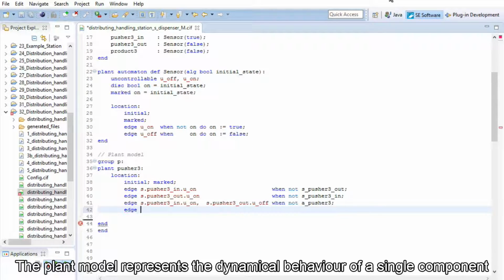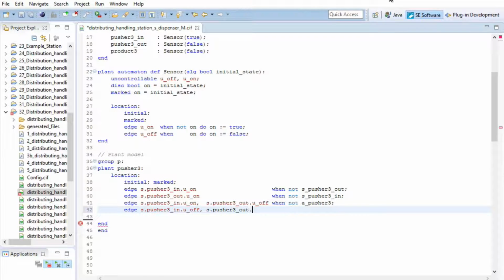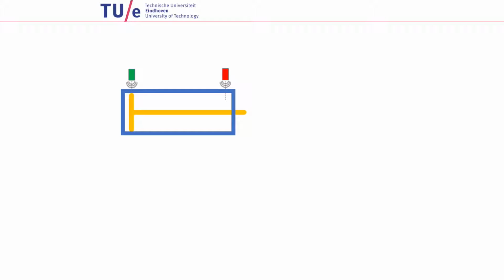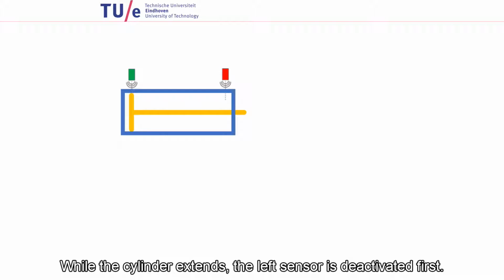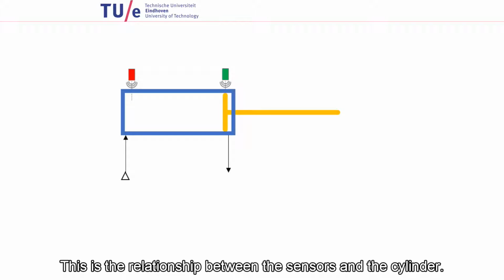The plant model represents the dynamical behavior of a single component and the relationship between different components. For example, here you see a cylinder with two sensors. When the cylinder is retracted, the left sensor is activated and the right sensor is deactivated. While the cylinder extends, the left sensor is deactivated first. When fully extended, the right sensor will be activated. This is the relationship between the sensors and the cylinder.